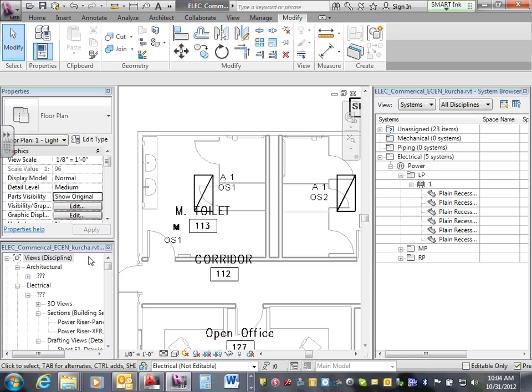So here's my question for Joe. Do we tag in the ceiling view? No, it doesn't mean anything. We're not printing from there. You tag in the floor view lighting. You drop the fixture in the ceiling view. You go to the floor view, you circuit, you switch, and you tag.